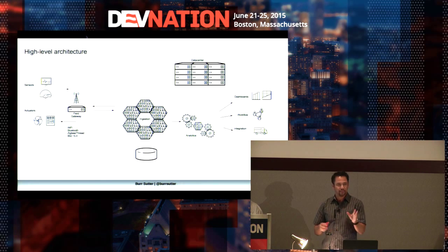So there's a third one that we might not be too familiar with because we're coming at this from a different world. It's called 802.15.4. It's a mesh networking protocol that you layer on with 6LoWPAN, and maybe CoAP on top of 6LoWPAN. And so now you have a mesh network. This is important because in an industrial setting, you're going to have a lot of RF interference between you and the thing you want to talk to, like we did here, right? And we used Wi-Fi. If we could use 802.15.4, we would have really killed it. It would have just really worked better.